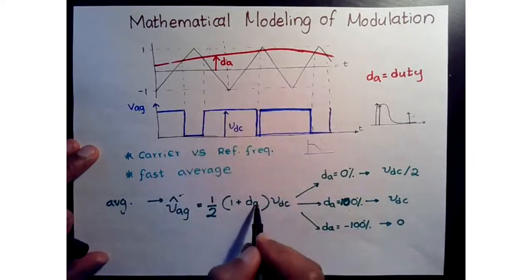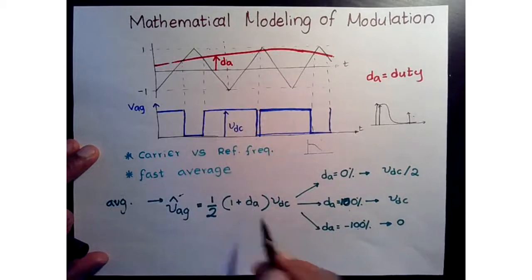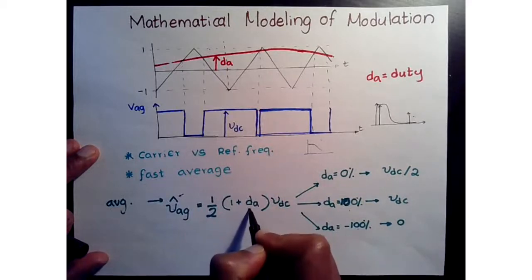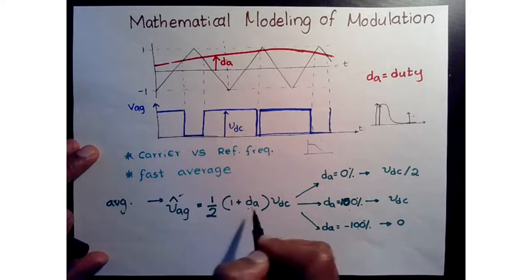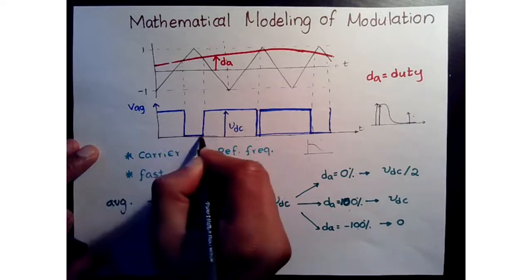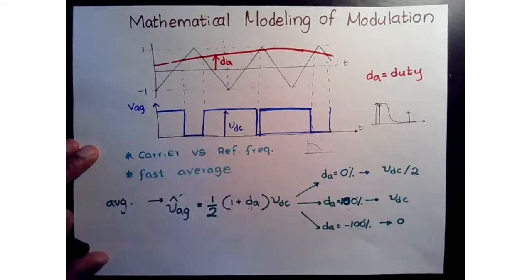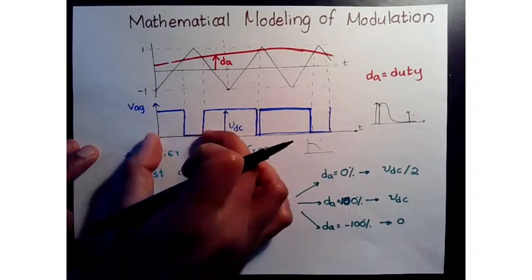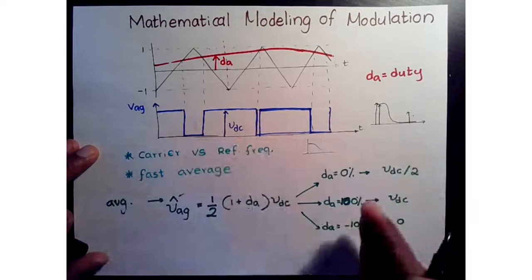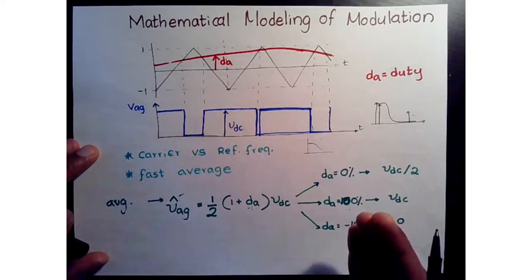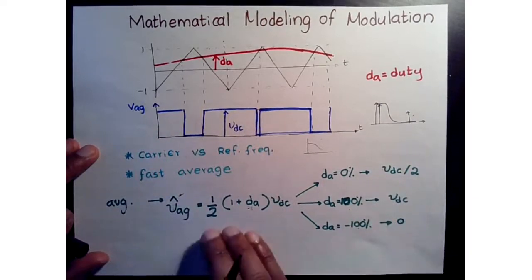That means this is going to be -1, right? That results in a fully off signal for the full period. So you will have 0 volts, 0 DC. When you average it, you're going to see 0 volts at the output of the bridge.